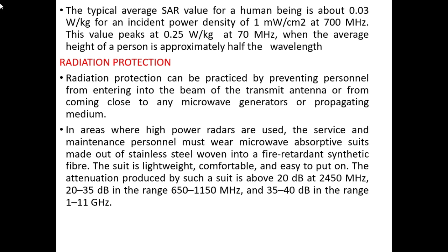Another way: when our work is in a radar design center where we test microwave components or devices, we can go for a microwave absorptive suit, which is made up of stainless steel and can be woven into a fire retardant synthetic fiber. This suit will prevent us from absorbing the microwave radiation to a greater extent. There are attenuation levels for the suit, depending on the frequency levels.